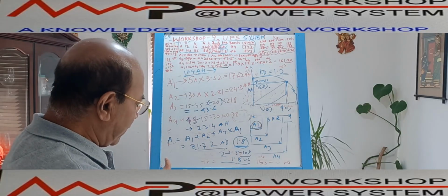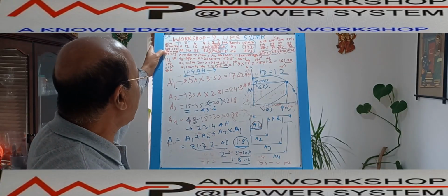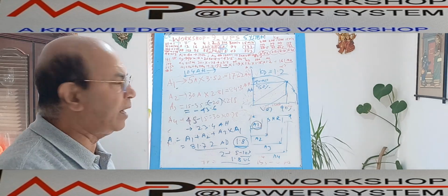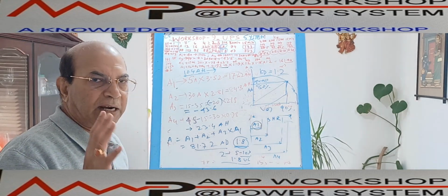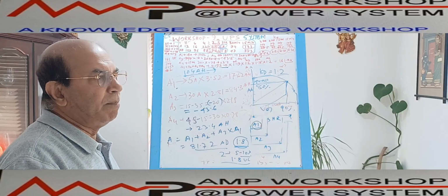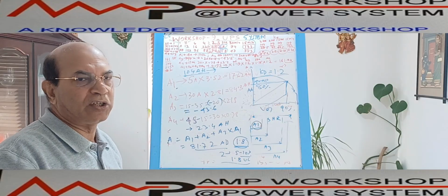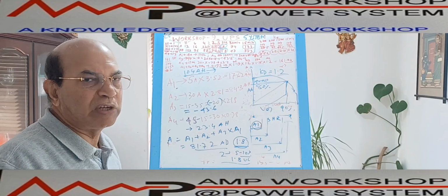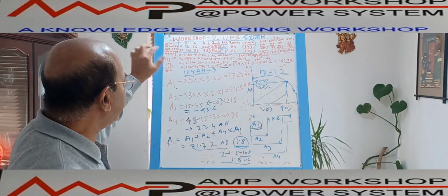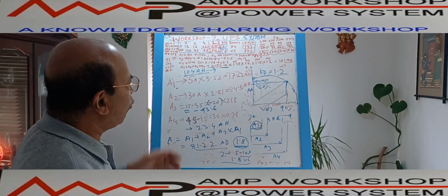Okay. Now the third point is the temperature. As we mentioned, this battery is operating at 10 degrees centigrade. We have already discussed all these points in video 79: the battery is rated at 25 degrees centigrade. At this temperature it will give its rated capacity, but if the temperature goes down, the battery capacity drops because the chemical reaction takes place slowly, so it will produce less current. How the capacity changes with temperature, we have shown. If I consider an operating temperature of 10 degrees, the factor is 1.19.